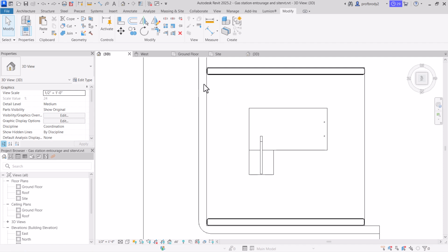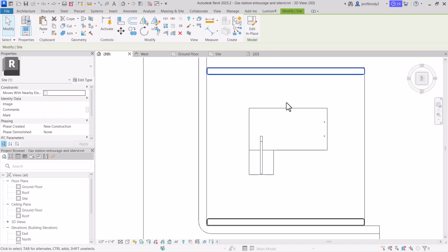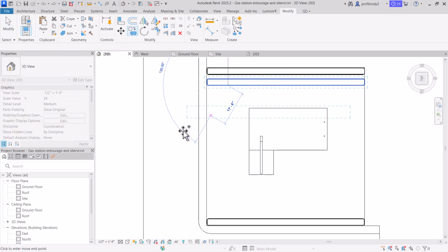There's these planters on either end, but I believe there are two curbs here, and this is kind of where people would drive through. So let's add those curbs, but boy, that's a lot of work to draw those curbs from scratch. Why not just copy these guys and adapt them? Now, I find this to be the fastest method. If you already have something, why not copy it?